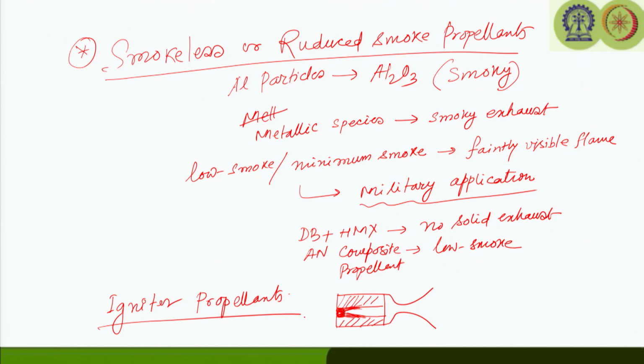So, these are the certain categories of propellants used for igniter composition. For example, some amount of boron particles are used as the fuel for igniter propellants. One such common example of igniter propellant is boron plus potassium nitrate, with some binder. Boron particles can be 20 to 30%, with about 65% of KNO3 and a small amount of binder, which forms the igniter propellant. Other ingredients have been tried to form igniter propellants. The main objective is to produce high heat release at a faster rate.